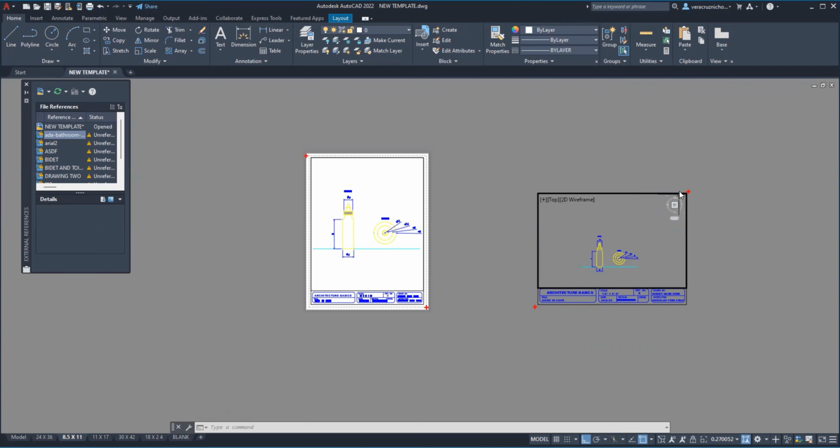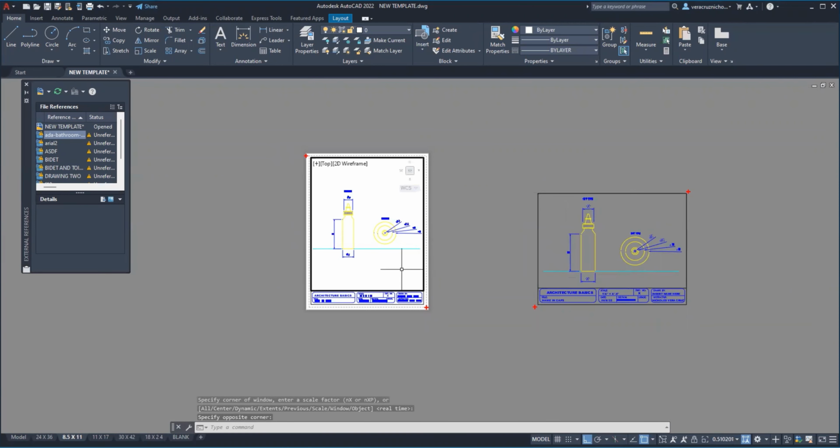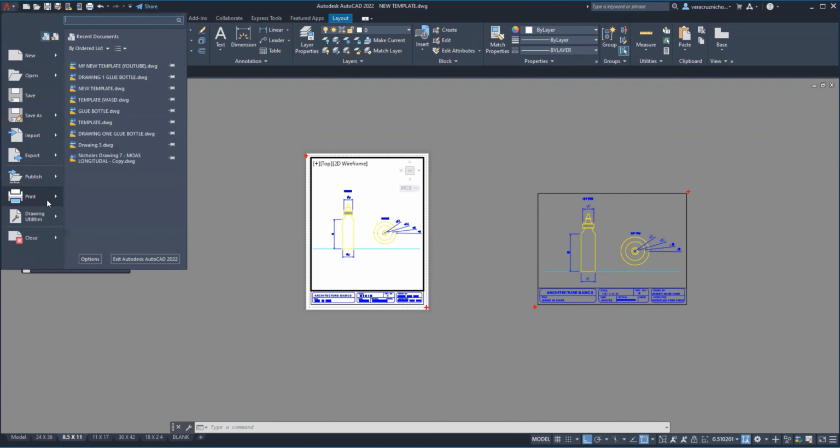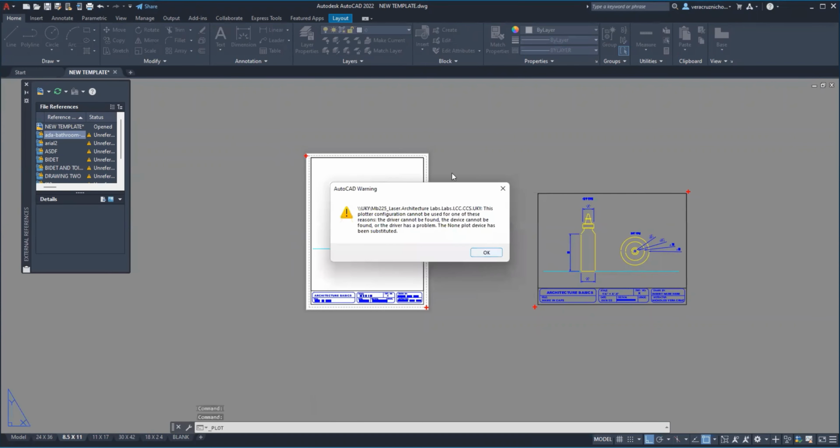You could tell which one you're going to click by seeing the black highlight around them. Right now, I'm going with this one with the black highlight. I could switch to this one. Instead of scaling to fit, here's another cheat code: Z, enter, Q, enter. That helps you scale it to as much as you can. That should be, there we go. But for right now, I plan on using this one on the left side. We're going to go to the AutoCAD logo, print.